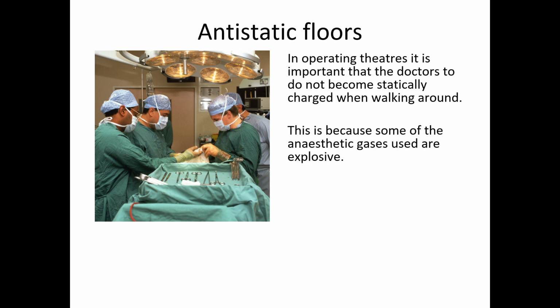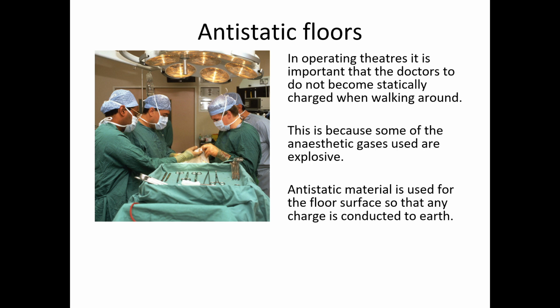Anti-static floors are something that features in things like operating theatres. It's important that the surgeons or the anaesthetist don't get charged up, because you don't want any sparks, and you don't want the anaesthetic gases, which are often flammable, to ignite.